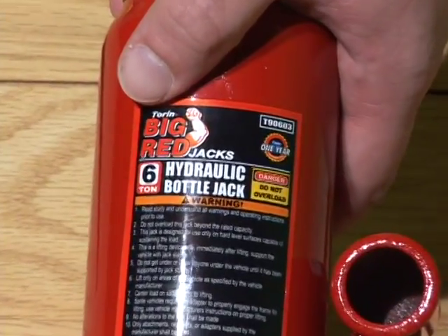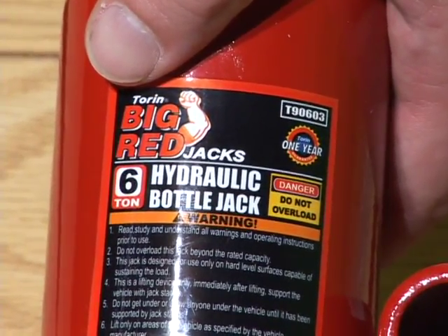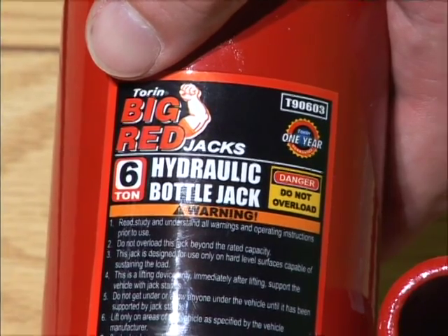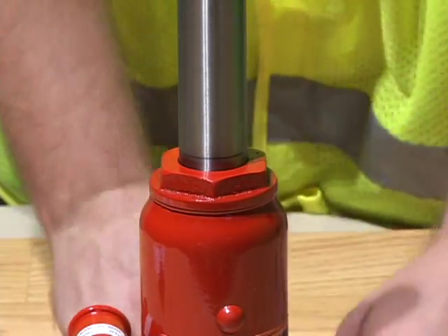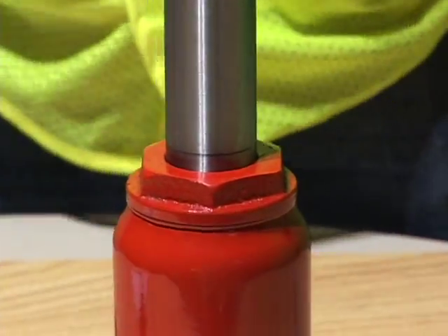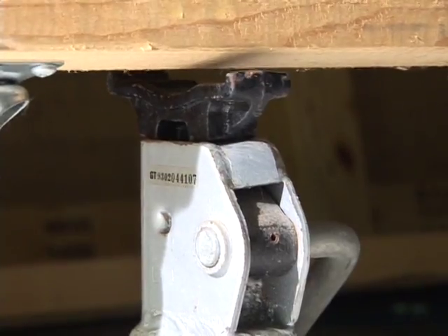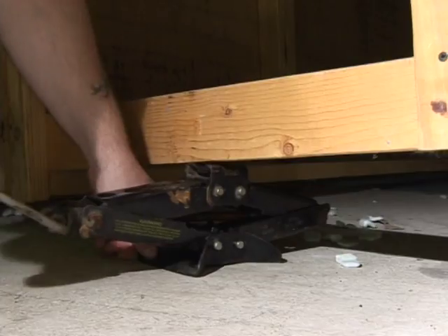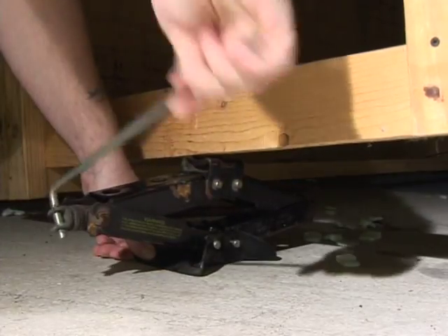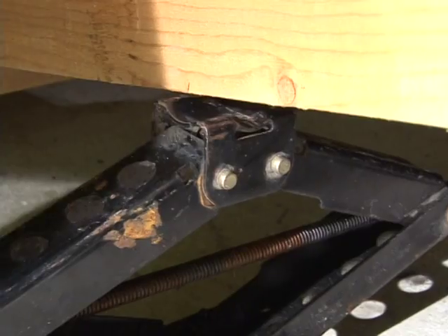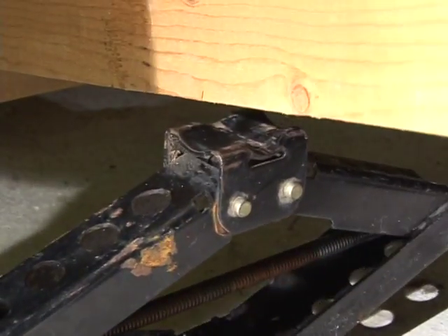Manufacturer's load limits must be permanently marked in a prominent place on the jack and should never be exceeded. Jacks should have a stop indicator that stops it from jacking up beyond its safe limit. Always block a load after it has been jacked up. Never rely on a jack to support the load. Block the load and remove the jack before proceeding.